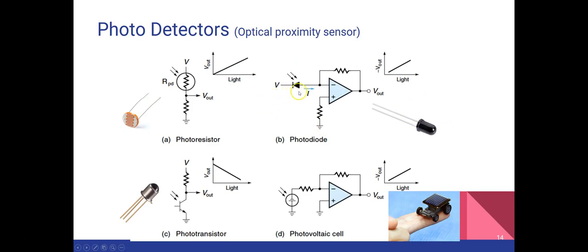This photodiode is a light sensitive diode, and a little window here allows light to fall directly on the PN junction, where it has the effect of increasing the reverse leakage current, and that reverse leakage current can further be sent to the next circuit attached to the photodiode.